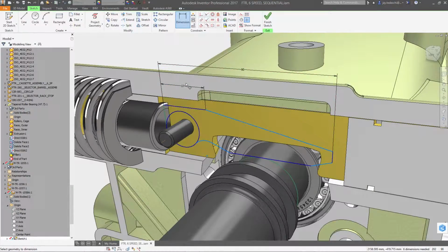You'll notice that as you sketch, you can dimension each feature as you create it, keeping your design momentum moving forward. You can also add intent by defining new parameters directly inside the dimension box, rather than stopping to open a separate dialog. Links between features can be defined as well. Clicking on an existing dimension creates the relationship, where you can then add equations if needed.